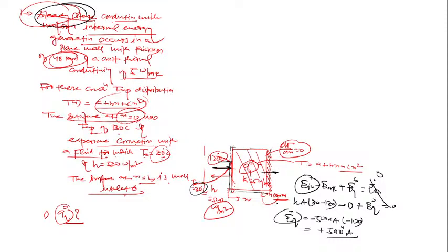So what is EG? EG is QG into volume. Generation volume is area into length. Length is given as 40 millimeter, meaning 0.04 meter. This area cancels. Can you find the QG? It is 5 into 10 power 4 upon 0.04. Tell me how much the answer is. This is through equations, very simple.